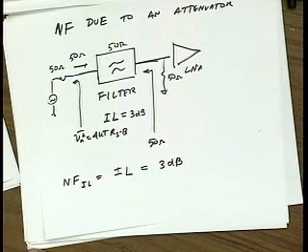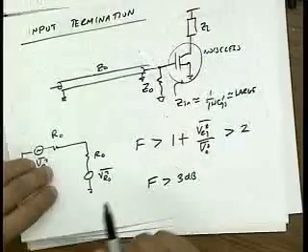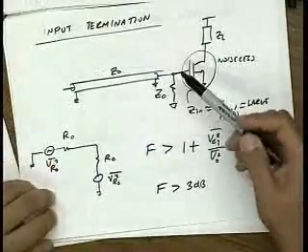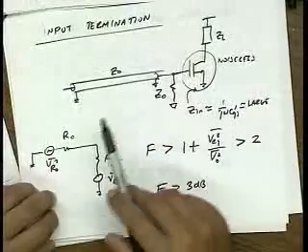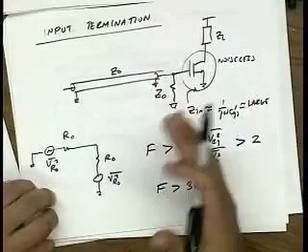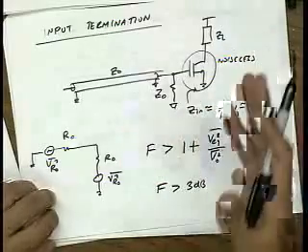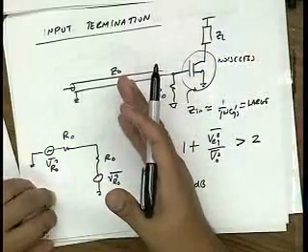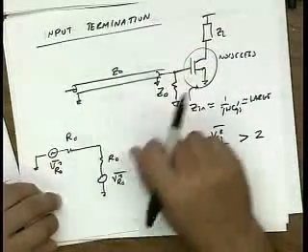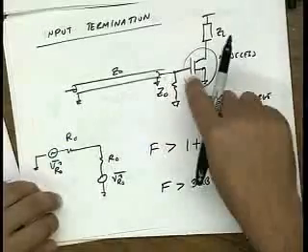Other questions? All right, so that means that when you put together a system, coming back to this original noise figure of 3 dB, you might find that it's too high. Because if you take into account the fact that the transmission line has some insertion loss, right? This is going to be some trace on a PC board like FR4 that has some insertion loss. You're going to put a filter in there, that's going to have some insertion loss. At the end of the day, you're going to have a few dBs of loss to add to the noise figure of the LNA.